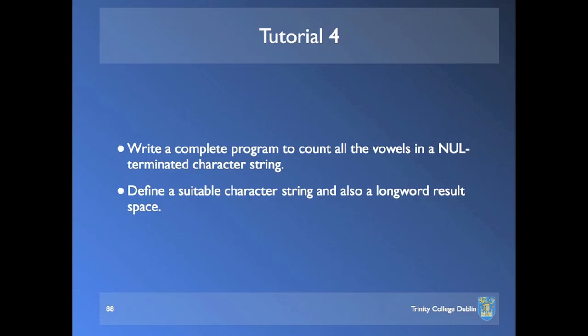If you're using their values for some purpose, the values have to have been set by you, like initializing a variable. You have to make sure that they have a sensible value in. Here, I'm using the add instruction, which does not use any of the bits of the condition code register at all. It does set them, but it doesn't use them. So this is the starting point. I'm just going to add those two numbers together.